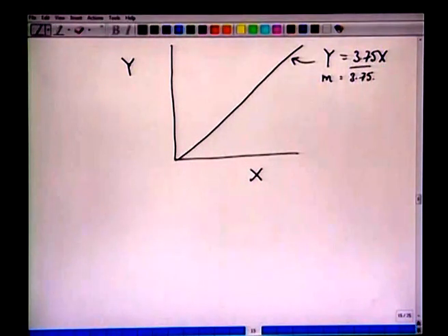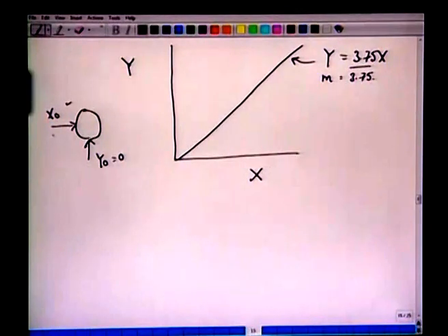Okay. Let us mark down the points, go back to this stage again. We have two streams getting in here: y0, the pure solvent, is 0, and x0 is given to us. So, we can mark it here. This is x0, and y0 is 0 here. This number x0 we know is 0.1765. So, that is a mole fraction, solid-free basis, in the feed.